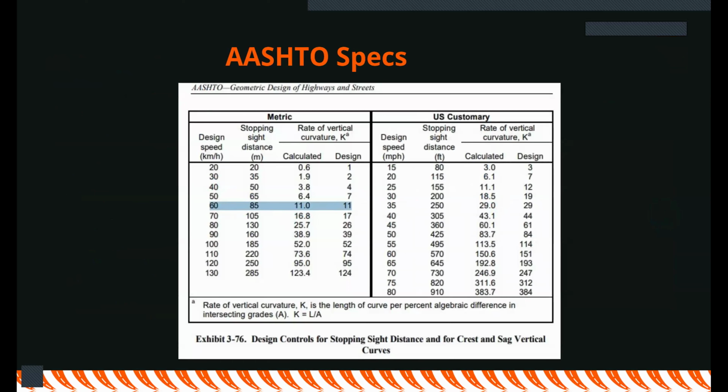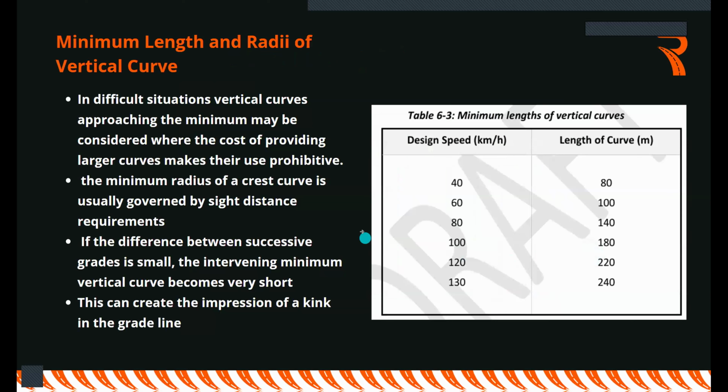Again, I would like you to check with your local road design manuals in Ghana, or whatever you're using. I think they still have very close parameters, because they have all derived their manuals from the AASHTO standards. In this case, you can see the AASHTO one is more optimized. So instead of 30, they are recommending us to use 26.